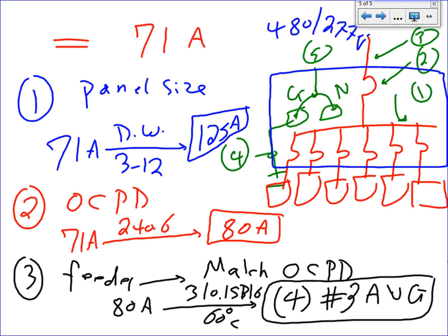Any question? So you'd have a 125 amp panel box, but it wouldn't have a main breaker in it. The breaker will be 80 amp. What's wrong with that? Why don't you just make it bigger, since it's small? Yeah, absolutely, that's exactly what we were just thinking, for future expansion.